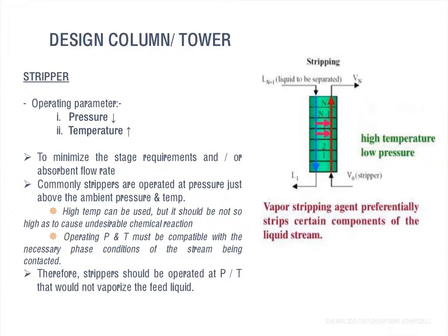This operating condition is opposite to what we have for the absorber. Therefore, strippers should be operated at a pressure or temperature that would not vaporize the feed liquid.